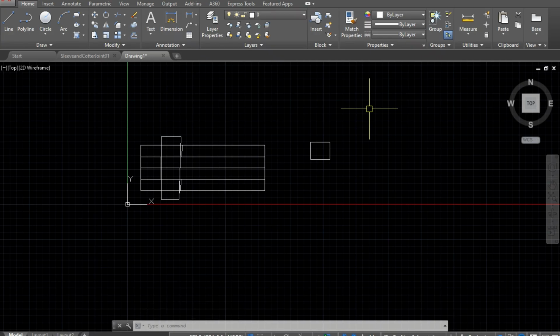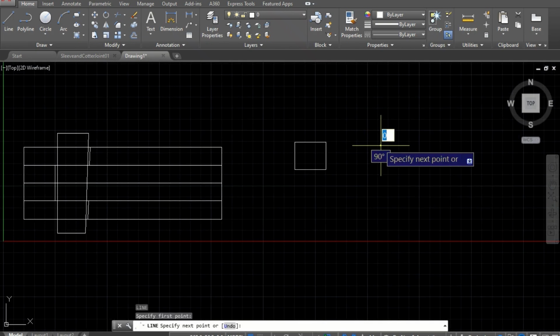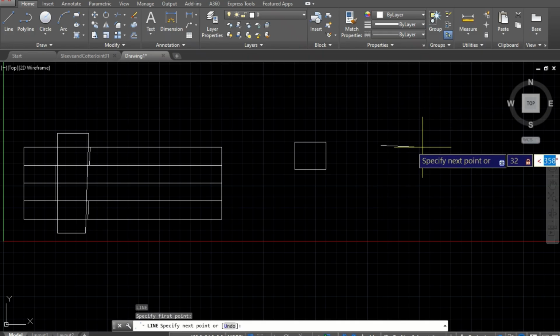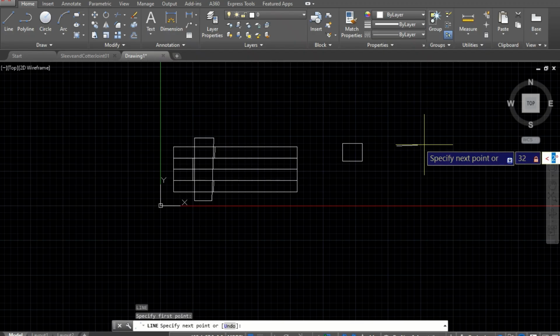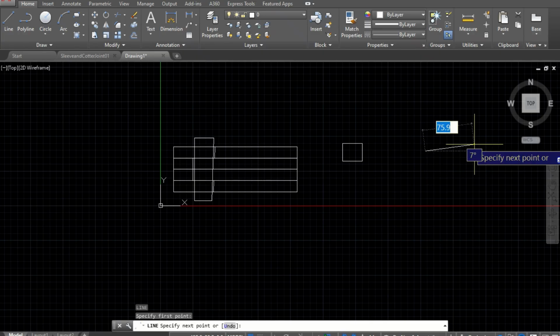The next thing is, let's create one more rectangle. Draw a line from this. This diameter we are given as 32. It should enter 32, right? So 32, and it can go at 65. Escape, draw a line, select any point, at 65 mm, 0 degrees.